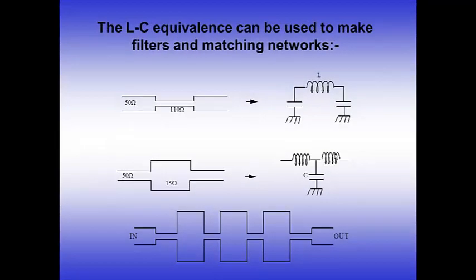So as one simple example of how we might make a circuit using a transmission line, this shows at the top a 50 ohm microstrip line with a small section in between of very high impedance microstrip. So if the width is very narrow, you have much less capacitance per unit length for the transmission line, and that small section of 110 ohm transmission line looks primarily inductive.